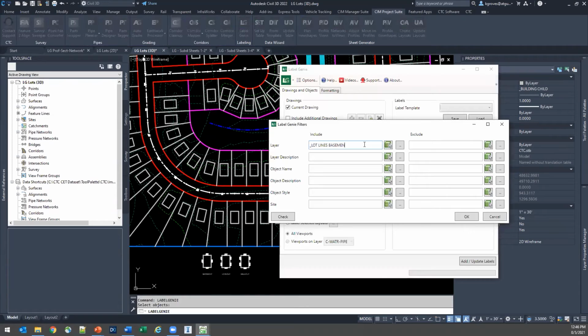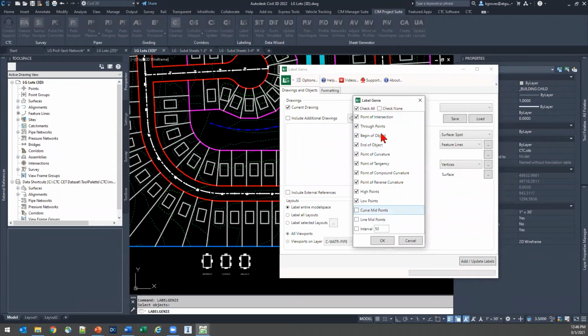And I'm actually gonna throw an asterisk because I have various scenarios. I have walkout basements, I have full basements, I have hybrid basements. And on these, I'm only gonna anchor basically my points. I don't want any midpoints, but I'll take any other vertex that I can find.